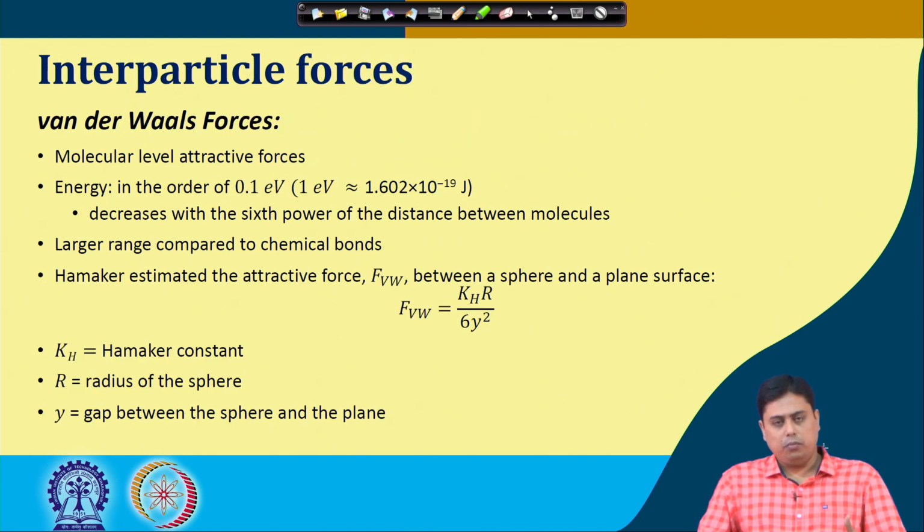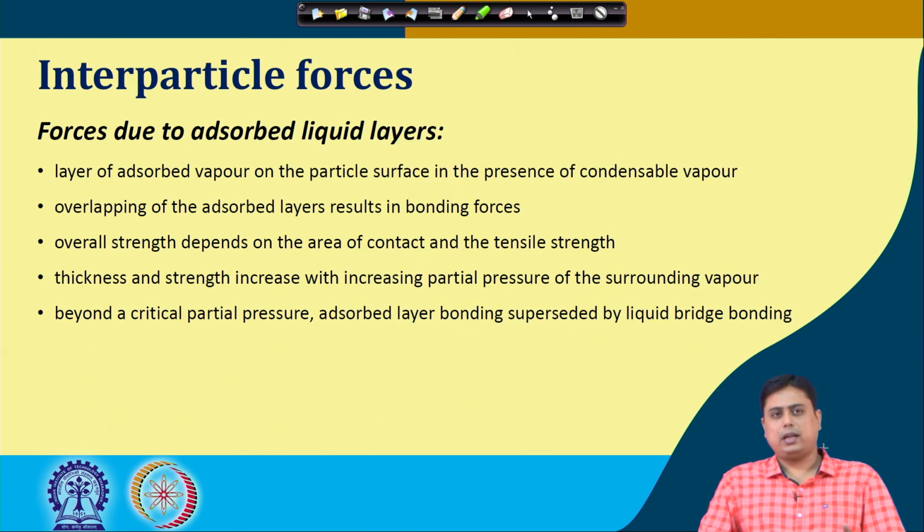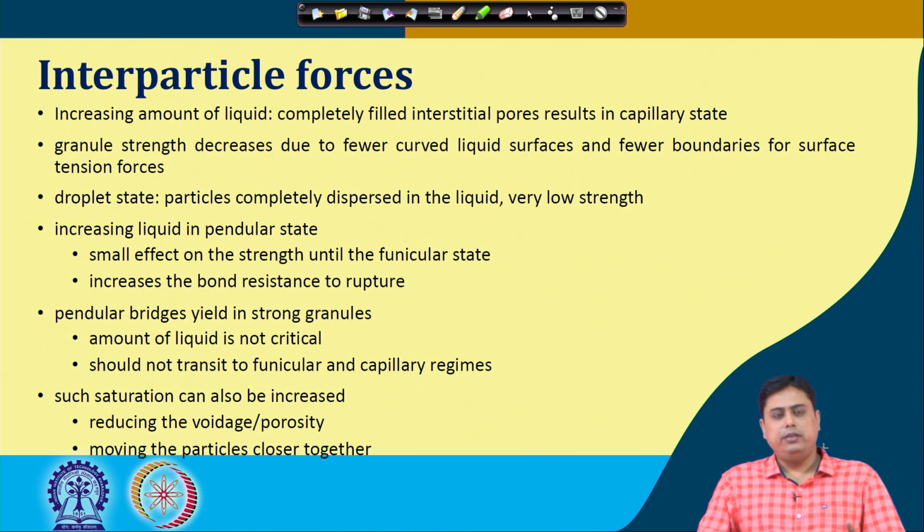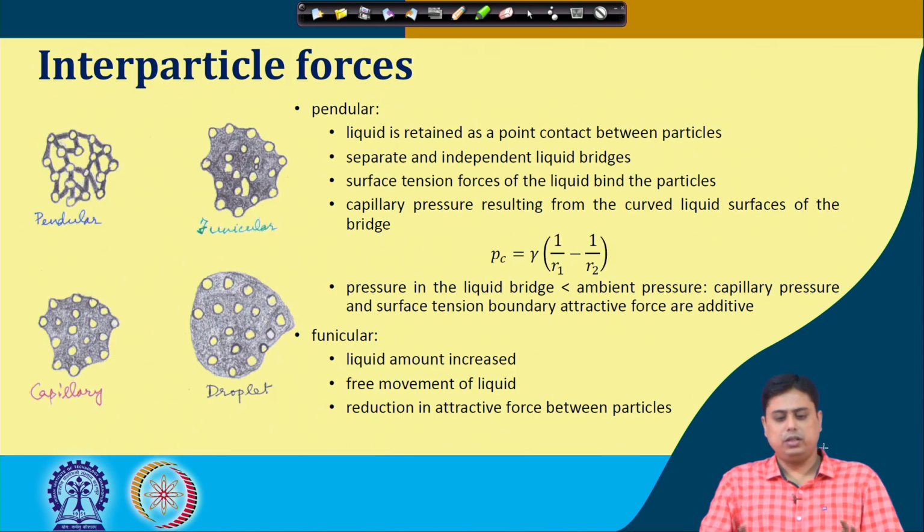So, before we introduced these steps, we have seen the overview of different interparticle or intermolecular forces that actually cause these particle interactions, the attractions or the repulsions. So, we have seen van der Waals forces, the forces due to liquid bridges, and different states during this wetting period, that is the pendular, funicular, capillary and droplet.